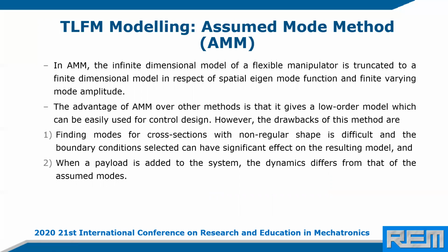Assumed mode method. In assumed mode method, the infinite dimensional model of a flexible manipulator is truncated to a finite dimensional model. The advantage of AMM over other methods is that it gives low order model, which can be easily used for control design. And the drawbacks are finding the modes for cross-section with non-regular shape is difficult. And when payload is added to the system, the dynamics differ from that of assumed mode.